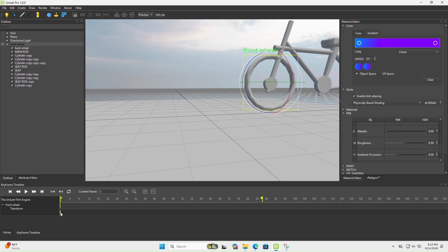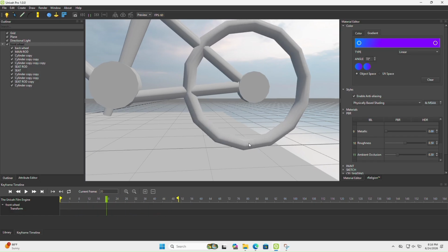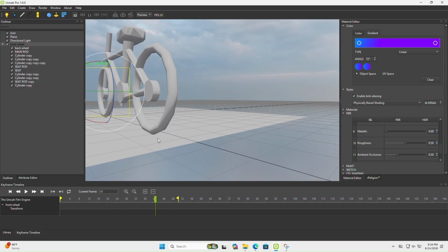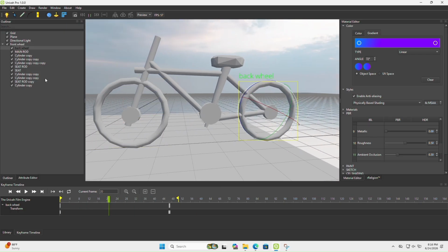You can also just hit the delete key to delete the keyframes. Let's drag this, hit the minus to delete that keyframe. So that's gone. You see, it's no longer moving. And we're just going to keep the rotation for the back wheel. I'm going to drag this end marker so that it has a perfect loop and maybe move it a bit more. So again, it's a perfect loop. Okay, good. So now we have a perfect looping rotation of that back wheel.